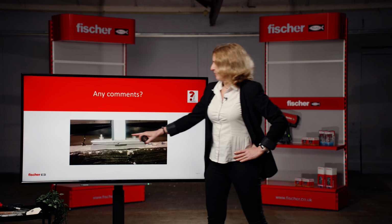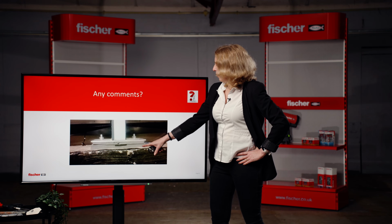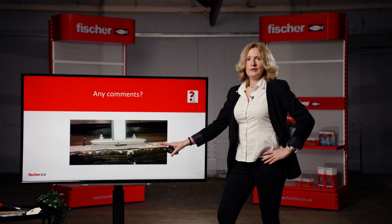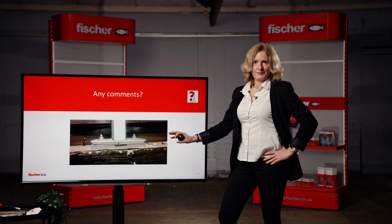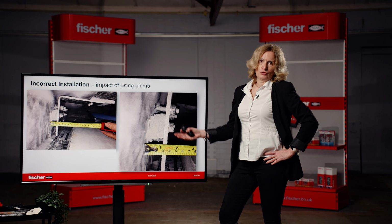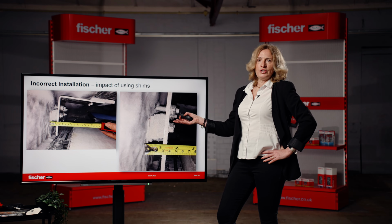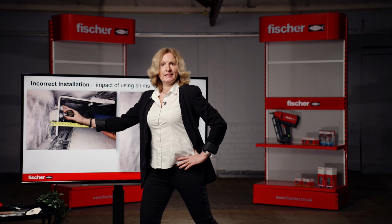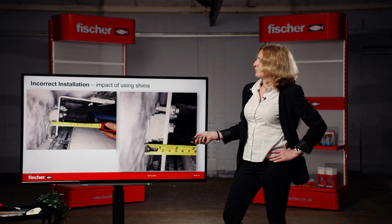You will see the base plate is not clamped directly against the concrete. We do have quite a lot of packing. That might influence the design of the anchor, especially if you have the load in shear. And this detail actually shows you how not to do it. You don't have to be a structural engineer to see that the bracket is not rigid, it will be rotating. So that is not the best detail for how packing should be applied.